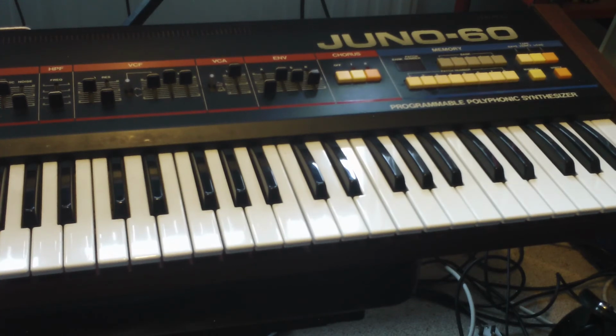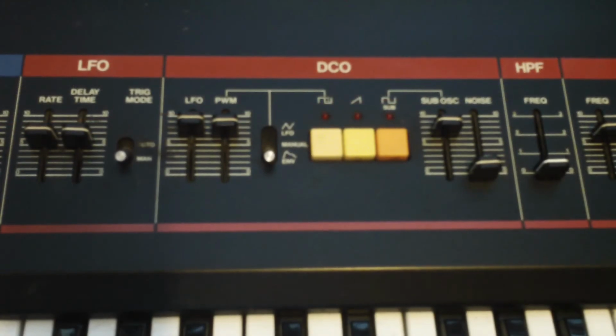It's a Juno 60. One problem with analog synths like the Odyssey and the Rogue is that as they heat up, the electrical properties of their circuits change, and that makes the voltage controlled oscillators in their circuits go out of tune. In the Roland Juno 60, instead of a voltage controlled oscillator, we have a digital controlled oscillator. This basically works on the same principle as your digital watch, and it means that it will always stay in tune.